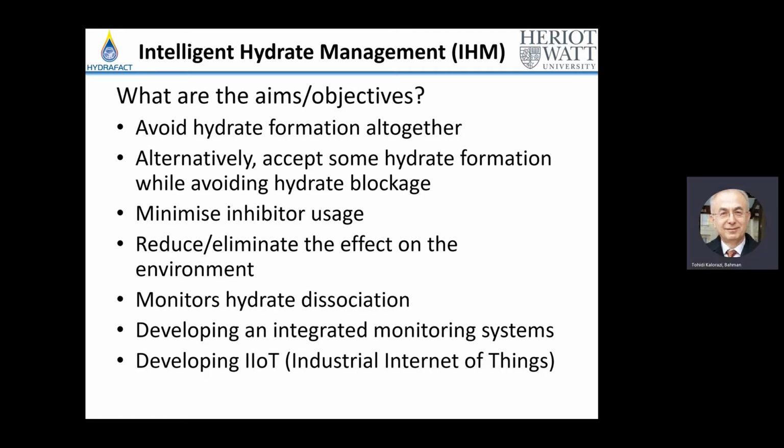So accept some hydrate formation while avoiding hydrate blockage could be a solution. Obviously, we want to minimize inhibitor usage, but at the same time, we want to make sure we have enough inhibitor.